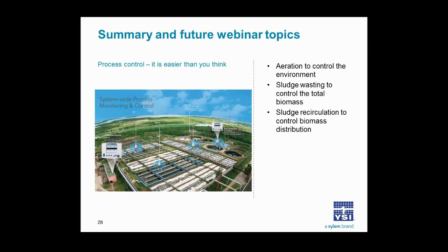So you're essentially losing anoxic zone volume by putting that high DO RAS back into the anoxic zone. So to minimize the volume, you want to minimize the dissolved oxygen concentration, minimize the nitrates, and minimize oxygen from other sources. But yeah, that really dovetailed nicely with some of the other topics.